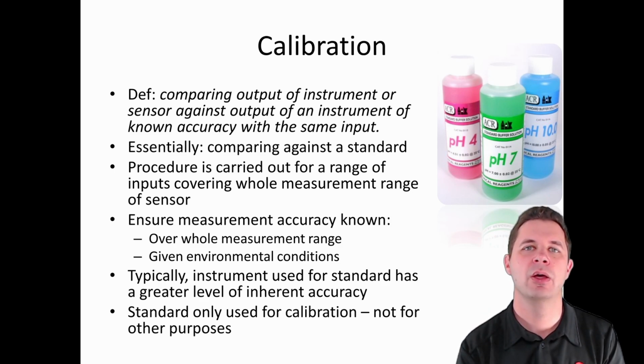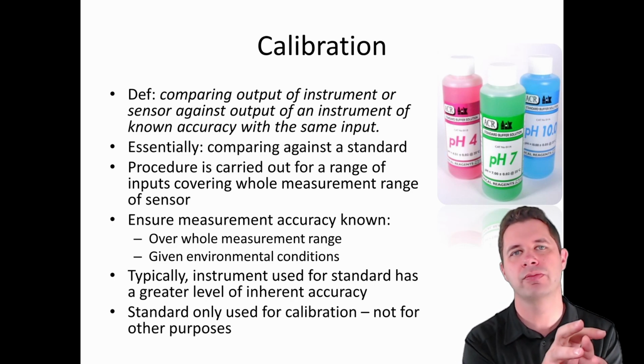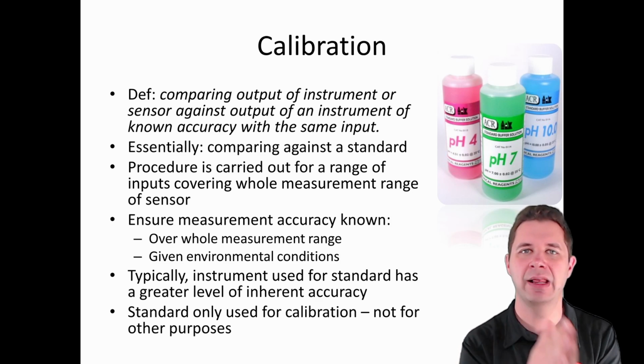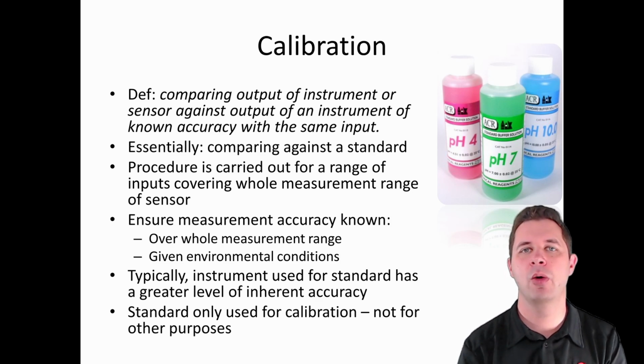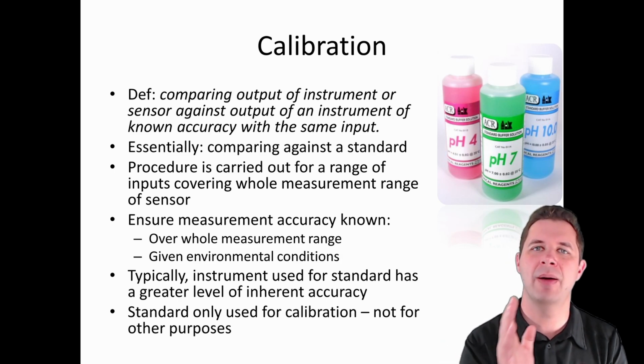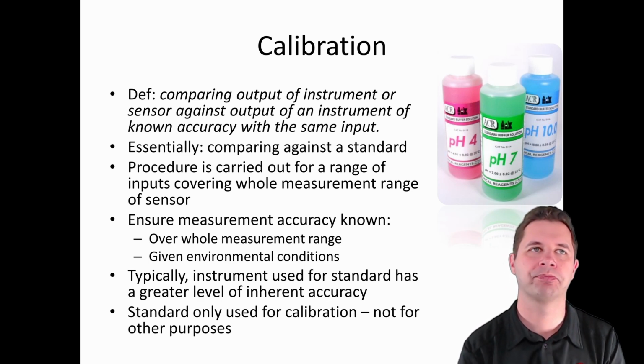each of them is. Once we've seen what the output is, we can compare those and adjust our actual sensor or measurement system to what the calibrated value should be. Once we've done that, we've essentially calibrated our system. So we have a series of set inputs. We'll expose these to our measurement system and our standard and compare the two of them.